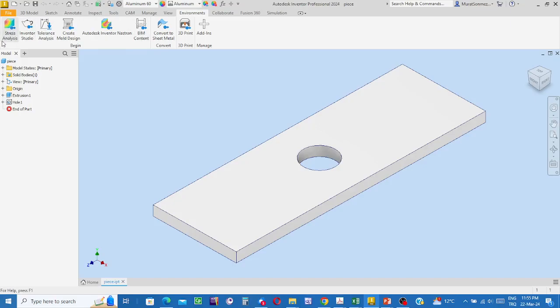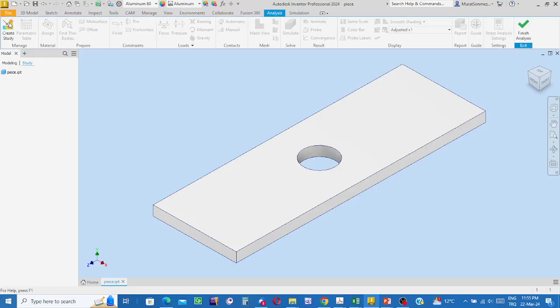There are lots of tricky details to know. Okay, first try to use the classical stress analysis tool of Inventor. When we run the problem, if you see that the yield limit will be exceeded, then change the analysis tool and use Nastran.